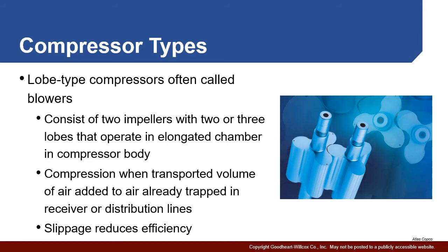Another form of rotary compressors is the lobe type compressor, as you see here on the right. These are devices where we have two lobed elements. They're interlinked together with a timing gear. They're designed to move within a housing. The housing is pretty closely fitting, but as you can see, there's a small gap here, and there's actually a small gap all the way around the outside.